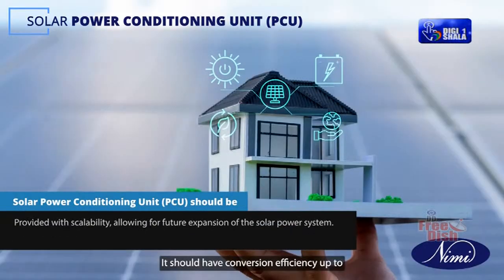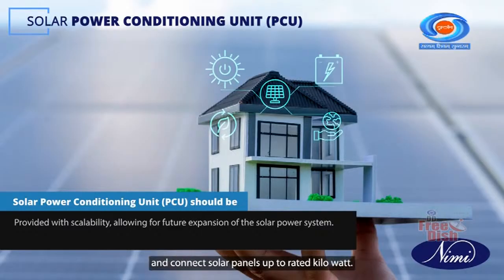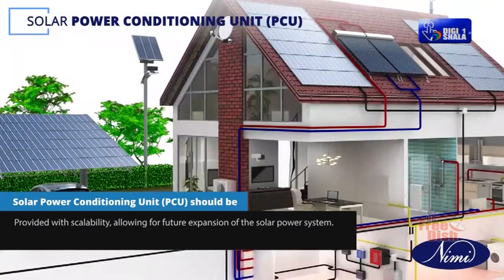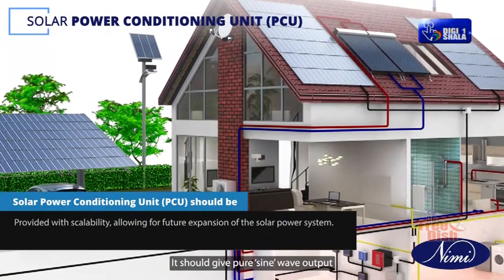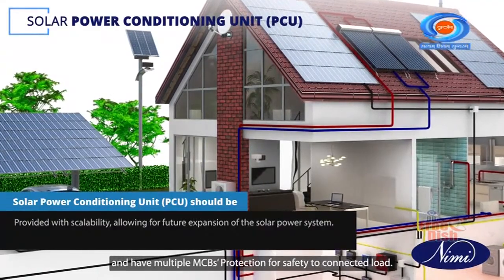It should have conversion efficiency up to 97% through MPPT technology and connect solar panels up to rated kilowatt. It should give pure sine wave output and have multiple MCBs protection for safety to connected load.